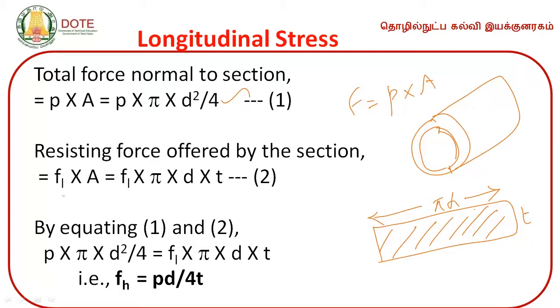So it is given by FL into A. Force is equal to longitudinal stress into area. So this is going to be FL into pi d into t. Now we can equate the two forces. By equating equation 1 and equation 2, we will get the value for FL.